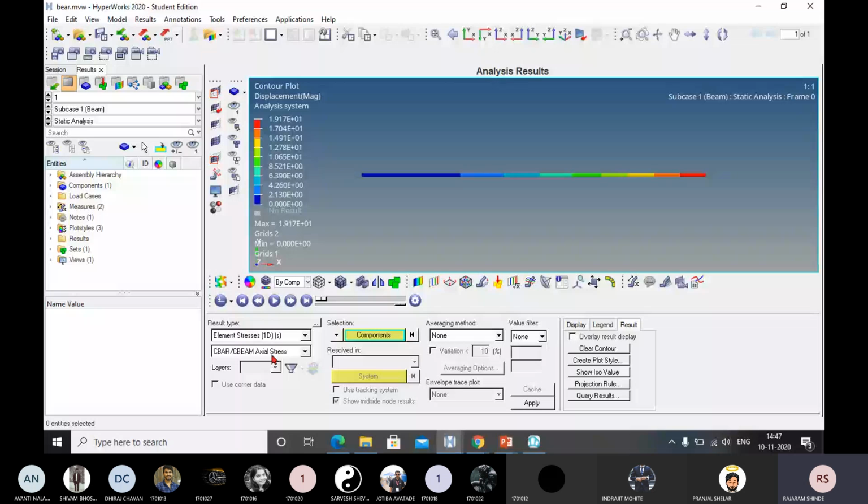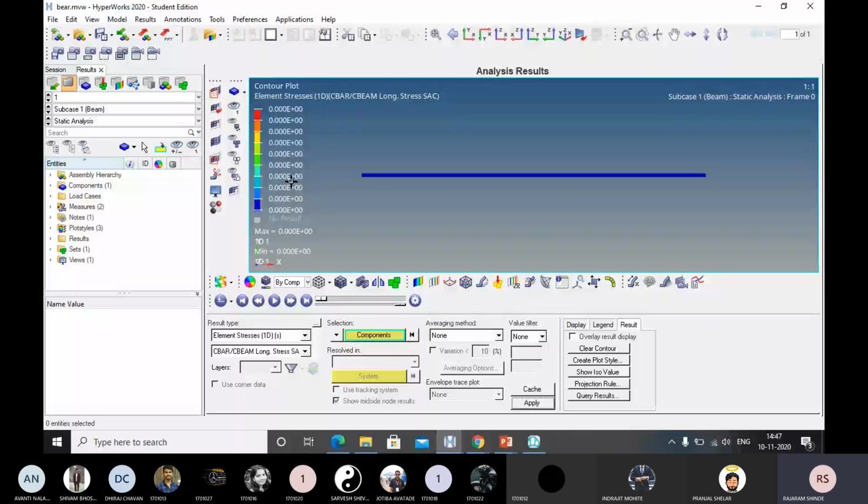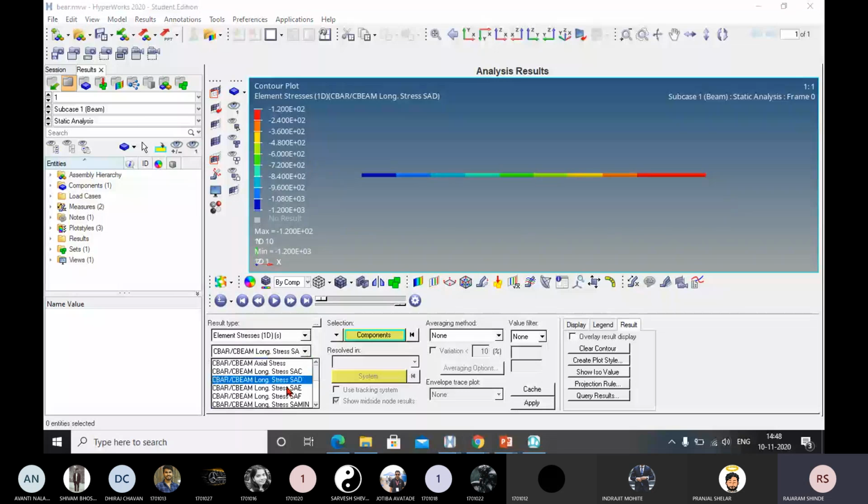See here also you will get the CDEF points. Now you get C point. At C it is 0 because we have used the orientation Z axis. Okay. At D you will get the maximum stress. You can see here, and it is not the same as the stress which we obtained in bar element because in bar we have Y orientation and here we have Z orientation. Okay. Now next stress at E, that is again 0, because your orientation is Z. At F you get this stress.